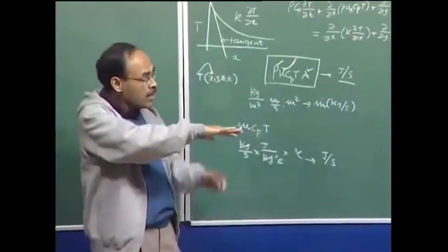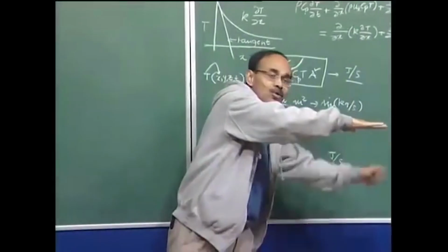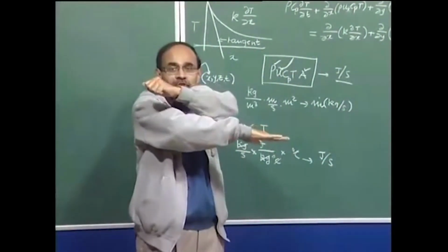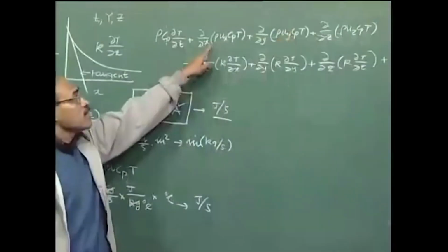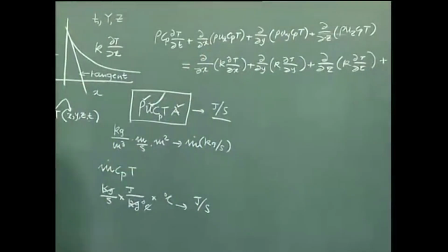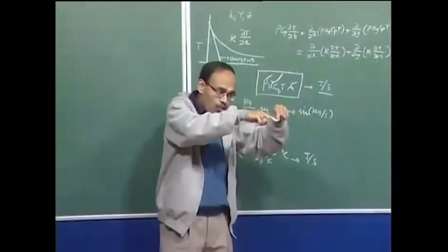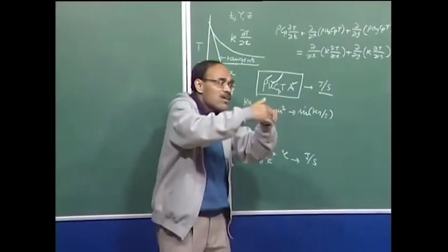But now imagine heat is flowing in this direction. So the fluid is flowing in this particular direction. So for heat to flow a large distance opposite to the direction of the flow is going to be very, very difficult. So this is the one way behavior of the term. This is the first order derivative. So the condition at a point will determine what is happening on this side of it. It is not dependent on this side.